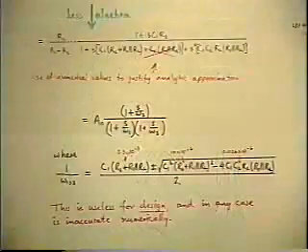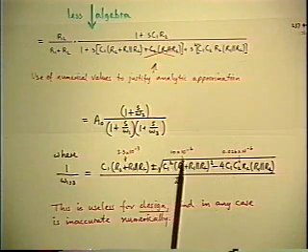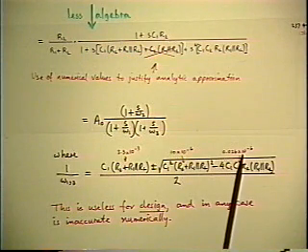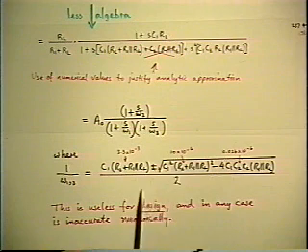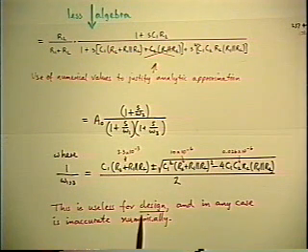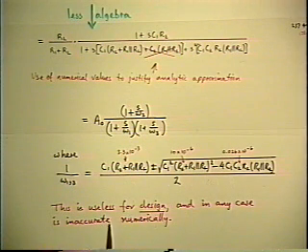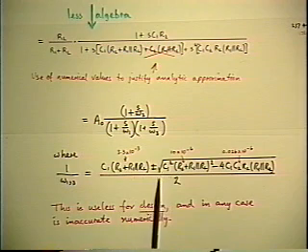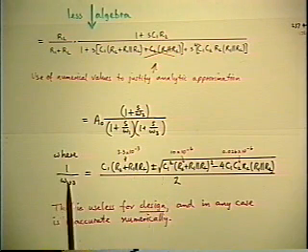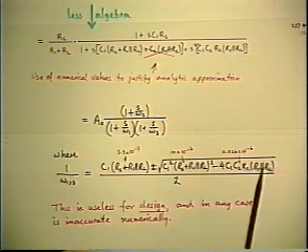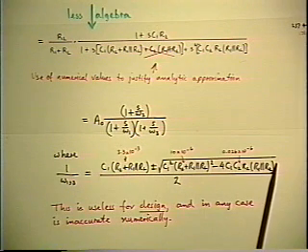You might as well have put the numbers in right away. And I've written over the expression what the actual numbers are. And the conclusion is this result is useless for design because you can't work it backwards. Knowing what the two corner frequencies are, it's hopeless to try to solve for any element values.